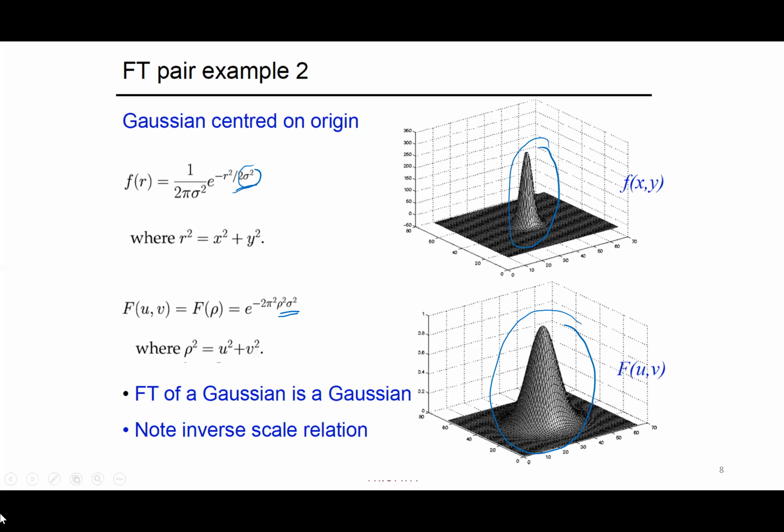Okay, sir, I got it. That means in the time domain, when the signal is real and even in the one-dimensional case, its corresponding Fourier transform is real and even in the frequency domain. In two dimensions also, is it the same? Am I right, Suman? Yes, sir. In two dimensions, if it is radially symmetric in the x domain, then it is also radially symmetric in the kx domain. Is that the analogy I was asking about?